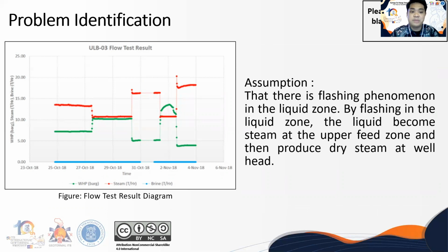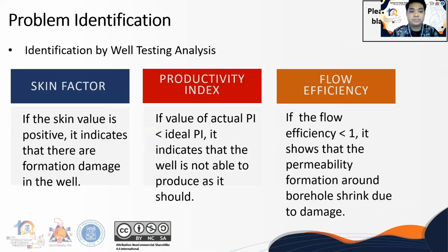Based on Abbott's paper 2007, one of the challenges of acidizing job in geothermal is that relatively faster corrosive properties occur. But in wells that only produce dry steam, the process of corrosion reaction will be much slower compared to wells that also produce water. So well X can be categorized as a good candidate well for an acidizing job based on corrosive properties, but other parameters need to be looked at.